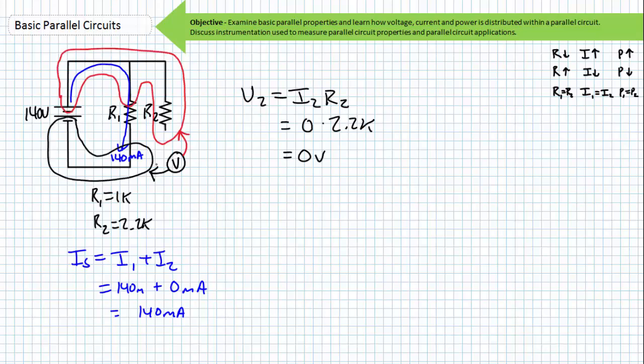This being said, since there is a voltage rise, there would still be a voltage drop across the open. With no current flowing through the second resistor, the only element drawing current would be R1. In this case, it is easily understandable that source current drops to 140 milliamperes because the removal of one of the parallel paths increased the total resistance.